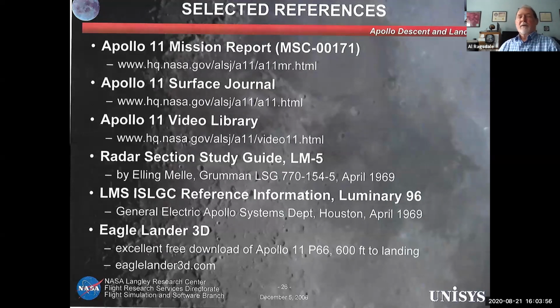And fuel slosh was another biggie. When Apollo 10 flew the mission before 11, they said that the fuel slosh was a lot worse than they expected. And so, around the time they landed on the moon, my job was trying to get a fuel slosh model in so they could fly it about 2 weeks before they went to the moon. But while we were doing that, Grumman was putting baffles in the tanks, so our model was wrong. So we had to keep tuning the fuel slosh model to match what happened.